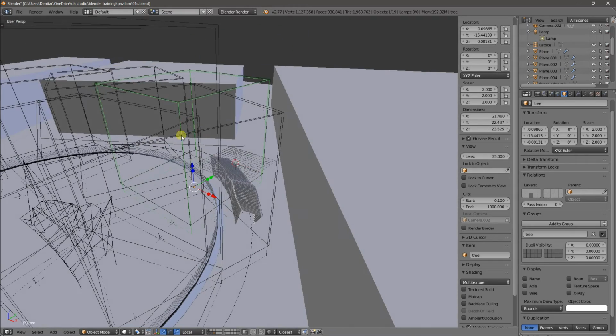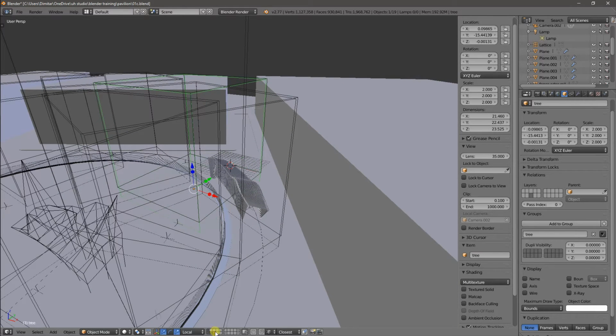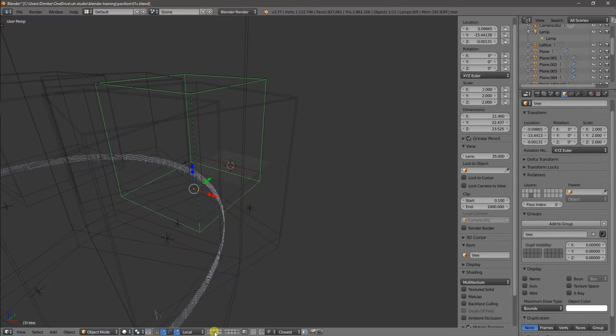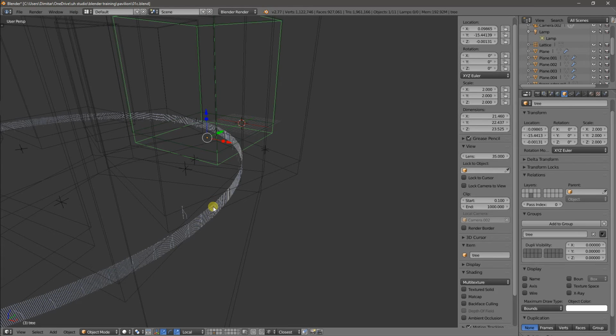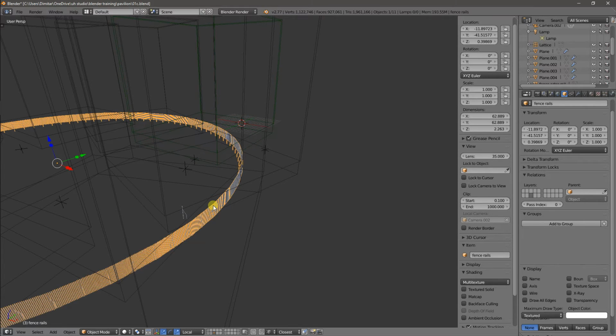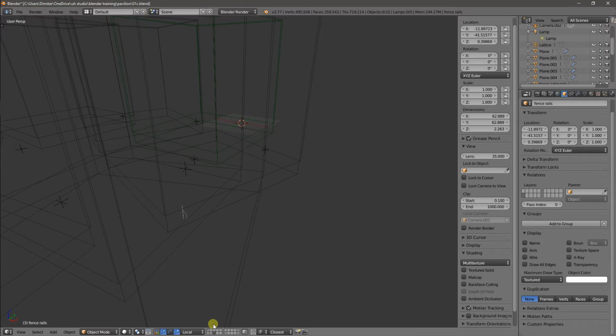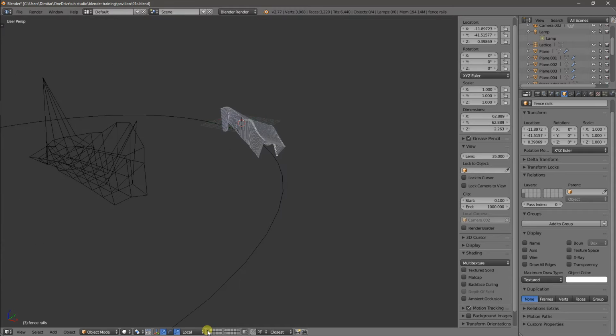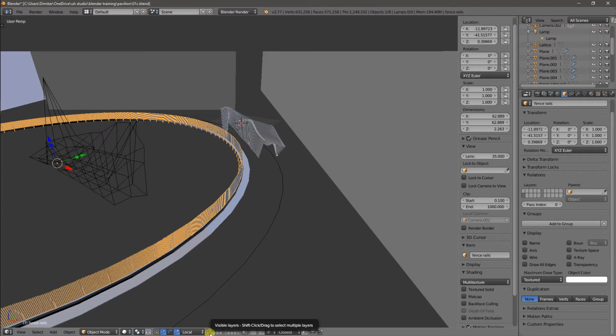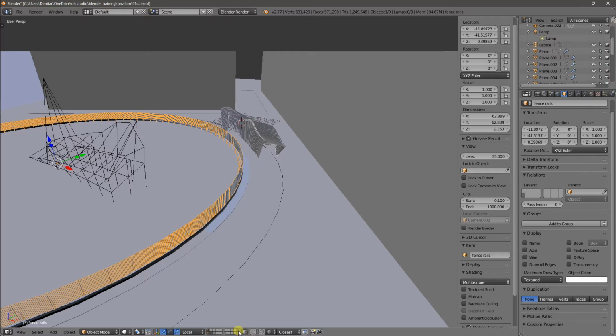And we also have the trees here that are represented as boxes. So the first thing we'll do is actually just turn off the boxes since they're a little bit heavy. If we go to the layer in which they're located, which is layer 13, we also have this fence, so I'll just select the fence and move it, M, to this bottom layer here. So now we'll work with this layer, and this layer. And our cameras are located in this far end.